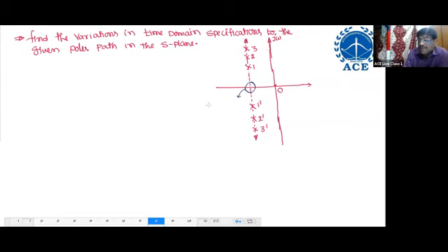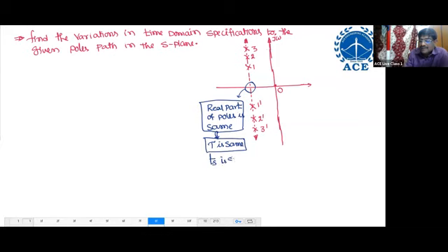As the real part of the pole is the same, the time constant is the same, tau is the same for all. As tau is the same, settling time is the same. So the real part of the pole is the same, hence time constant and settling time are the same.